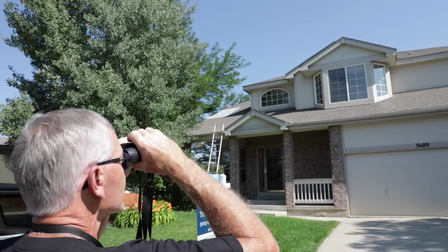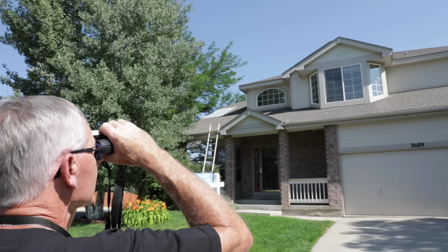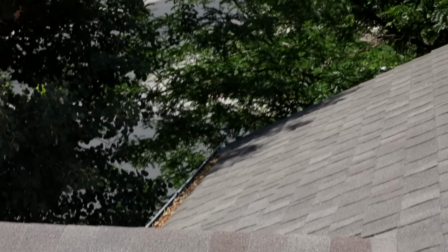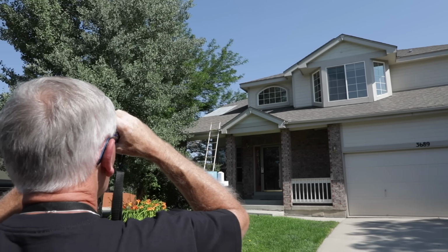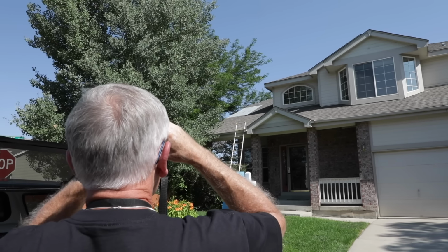And the first thing I'm noticing right away is I've got some obvious surface damage that appears to be from a past hailstorm. I'm working my way across the front section of the roof. I've got some loose shingles, and I've got a temporary patch on the roof too that probably was put on to stop any leaks that were caused by the hail damage.